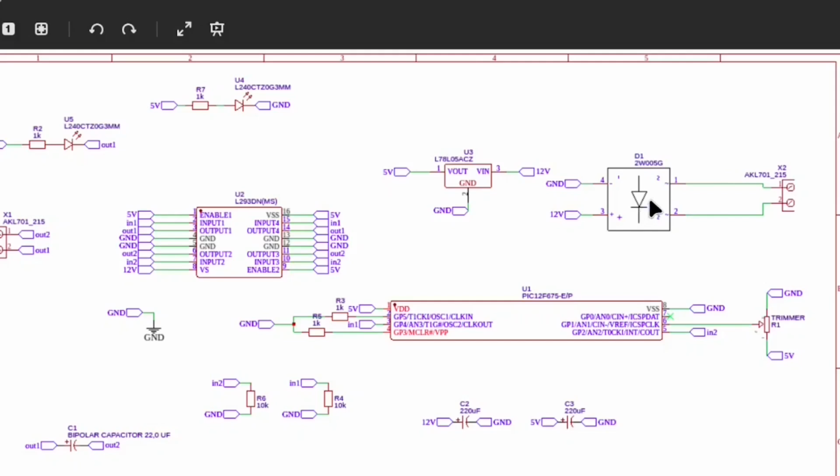It runs through this full bridge rectifier, which produces a ground output and a 12 volt output. The 12 volt output goes into this voltage regulator, which generates 5 volts, which is used by the rest of the system. Everything else runs on about 5 volts. The PIC microcontroller controls the timing of the outputs of the motor driver. The timing is derived from this trimmer pot setting.